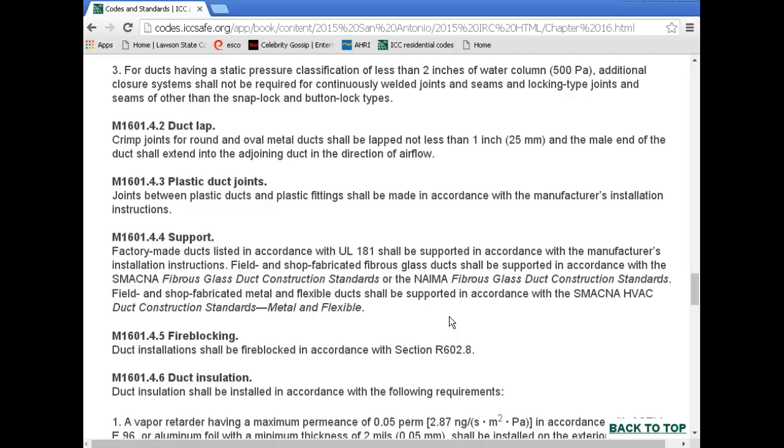The only reason I say this is because unless they just updated, if this is a test question, they're not going to have this. The interval is what, 10 feet? Not exceeding 10 feet. So if you went every 8 foot, you'd be good. Yes, half-inch straps of 18 gauge metal, or 12 gauge wire, and the interval for that hanging is not to exceed 10 feet.